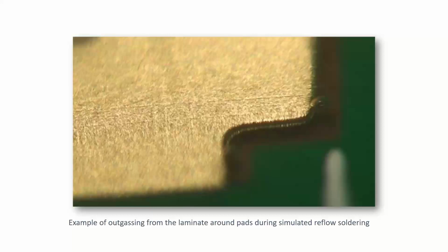So in the situation that the company showed me, I would certainly look at what we can do about the vias, check outgassing for the vias. If we can prevent solder paste sealing the gap between the via and the package, if we can eliminate the board creating the outgassing within the solder volume, which it clearly would from the vias, that's another thing to look at. And also compare the amount of voiding with pads that have vias in and pads that don't have vias in. So that is what I would do if I was looking at this particular problem again.